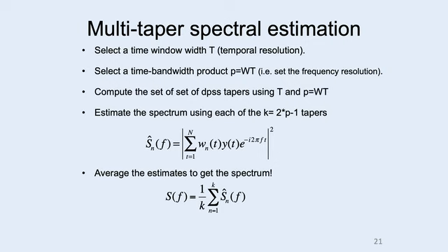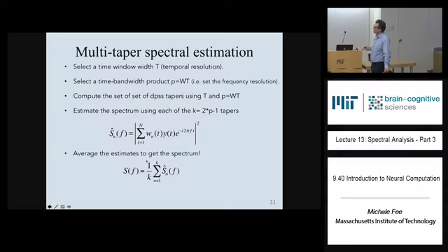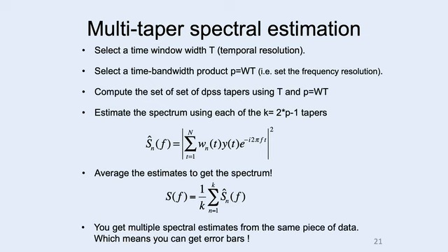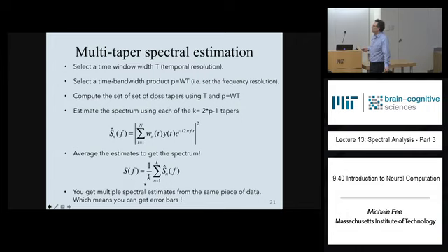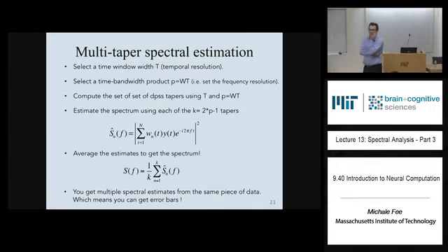I see, this is the Fourier transform right here. This sum is the Fourier transform. We square magnitude that to get the spectral estimate of that particular sample. And then we're going to average that spectrum together for all the different windowing, tapering functions. Okay? Now, you get then multiple spectral estimates. You're going to average them together to get the mean. And you can also look at the variance to get the standard deviation. Questions? I'll stop there. That was a lot of stuff.